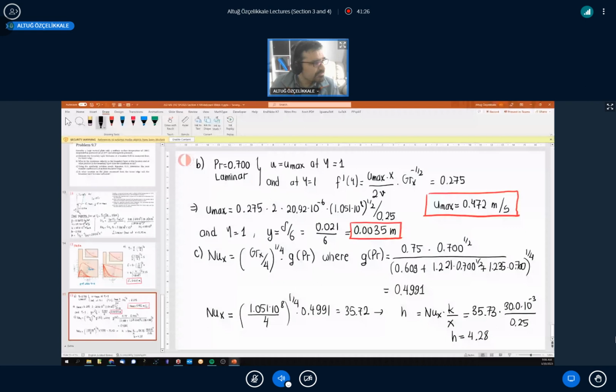A lot of things happen in free convection. Once we don't have forced convection, what we have at our disposal is free convection. That's the way a lot of power systems are cooled down, let's say in external space, like in ambient temperature, right? So that's watt per meter square Kelvin. Even though convection coefficients are low, that doesn't mean that they are insignificant. They are the main driving effect for heat transfer for many applications.